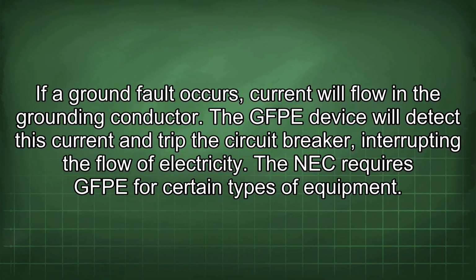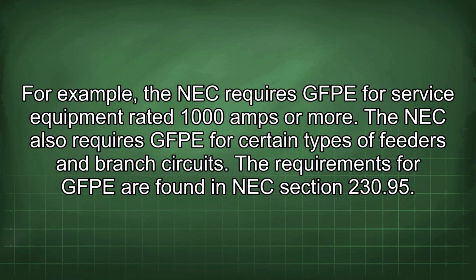The NEC requires GFPE for certain types of equipment. For example, the NEC requires GFPE for service equipment rated 1000 amps or more. The NEC also requires GFPE for certain types of feeders and branch circuits. The requirements for GFPE are found in NEC section 230.95.